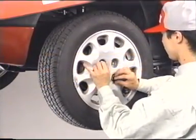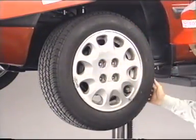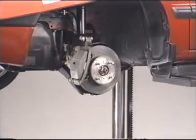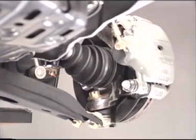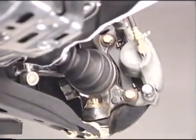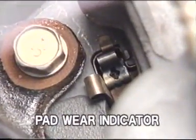Worn-out pads or oil or grease on the lining could cause inefficient braking. If the lining pad sticks, brake grab, squealing, or chattering could result. In the front disc brakes, a pad wear indicator is provided to alert the driver that the pad needs to be replaced.